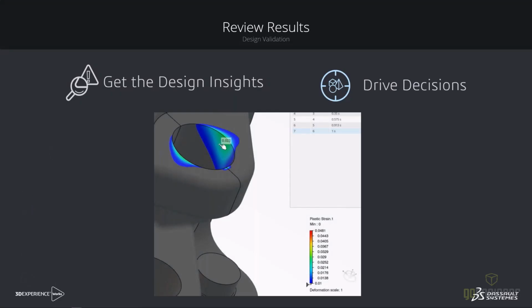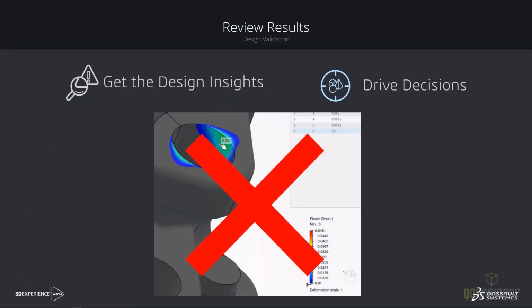Unfortunately, the model indicates plastic strain in the analysis. So this means that area of the model is, of course, yielding. So armed with this information, we can make some edits to the design to increase the rigidity of the model.